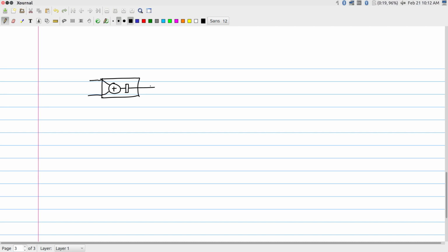All that I am saying over here effectively is that the two inputs, rather than drawing multiplexers, I am going to use a slightly different notation. I'll use some kind of switches to indicate that these are switches rotating across different phases, 0, 1, 0, 1 and so on. A multiplexer is how it is finally going to get implemented, but another way of looking at it is to think of it as rotating switches where you are just going through different phases cyclically. So there is a phase 0 and a phase 1. Similarly, there is a phase 0 and a phase 1.